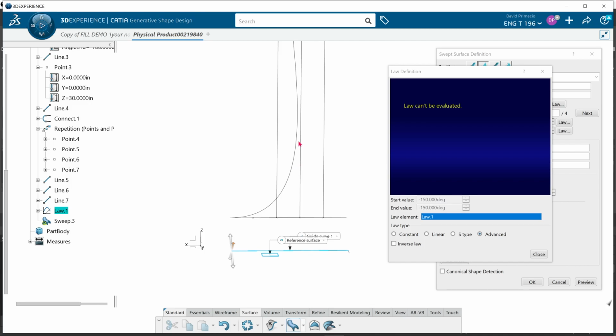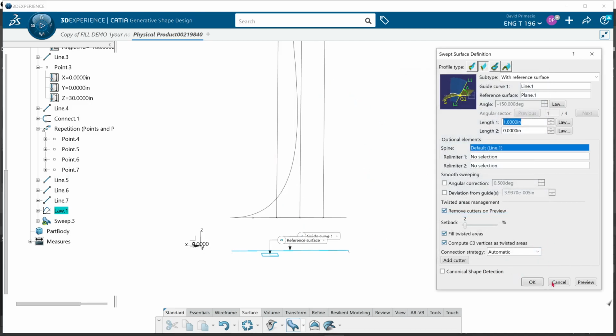So if you had a 1/2 inch radius on one end and a 1 inch radius on the other end, halfway through would be a 0.75 radius. And this would hit it right dead center in that middle. Same with if you did a length of 1 inch on one side, a length of 2 inches on the other side. When you project from the middle, it will find the intersection at 1.5 inches and define the length of the line transitioning from a 1 to 2, and it would be 1.5 right in the 50% ratio. Okay, so that law won't work because this crisscrosses on itself.